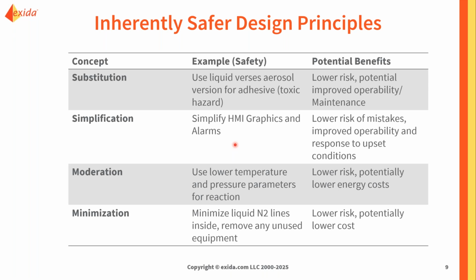And we've seen over time that the design guidelines for HMI graphics have moved away from having many colors and flashing lights to using more of a grayscale, providing the key information on that page for the operators to see everything coming into and going out of a unit. And through that, we've simplified their view of the process. We've made it easier for them to make informed decisions and lowered the likelihood for a negative impact.